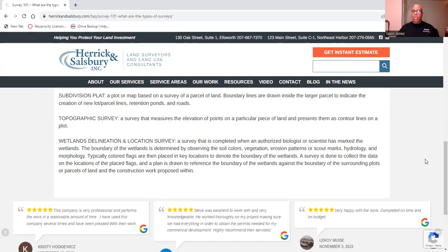Let's say you're shooting the edge of pavement, where you're going to be coding that point as EP. What if you're shooting a building corner? You might say building corner. But all those points that you shot, they're going to come with a code sheet based on the software that you're using, because of those points that you shoot out in the field, when you form that map,